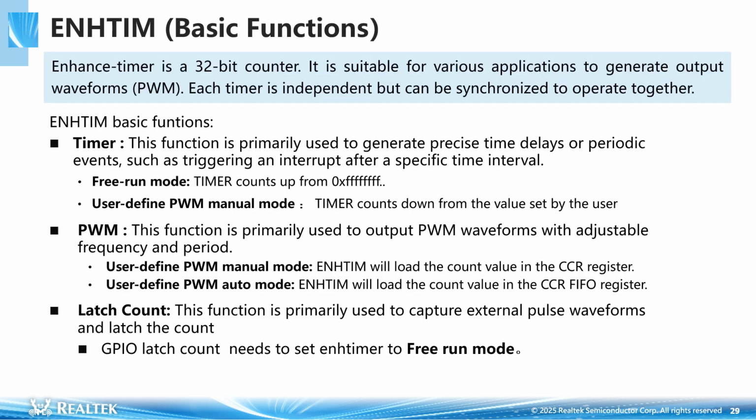Enhanced timer is a 32-bit counter capable of dynamically generating PWM waveforms. Each channel is independent and can operate simultaneously. The main functions of the enhanced timer include 3 types.